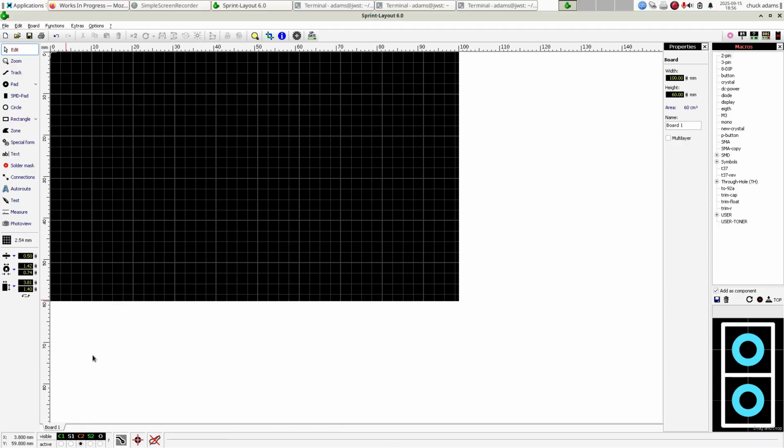Also, I use 2.54 millimeter headers, both female and male, as connectors and everything, because for most of my little experiments, I don't need everything to be permanent. And I can switch between power supplies and headphones and all kinds of things I'll show you through this series.